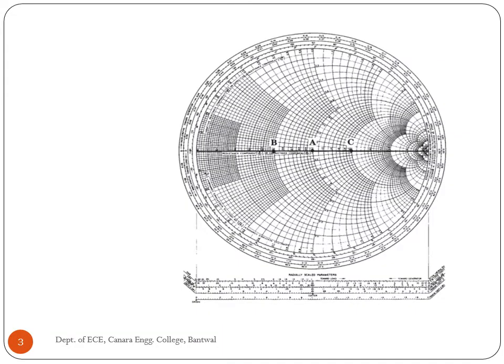The modern Smith chart is shown in the figure and consists of a series of overlapping or orthogonal circles, that is, circles that intersect each other at right angles. The set of orthogonal circles makes up the basic structure of the Smith chart. A baseline or center horizontal axis is highlighted in this figure and it bisects the Smith chart outer circle.